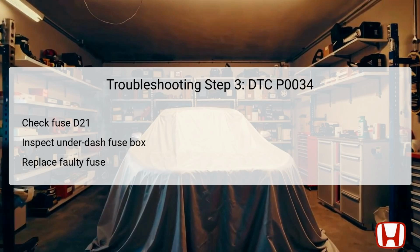Inspect the fuse visually to determine if it is blown. If the fuse appears intact, proceed with testing to ensure it is functional. Conversely, if the fuse is indeed blown, repair any short circuits in the IG1 ACG, IG1 ABV wire leading up to the fuse. Additionally, replace the blown D21 fuse to restore electrical supply to the solenoid valve circuit.